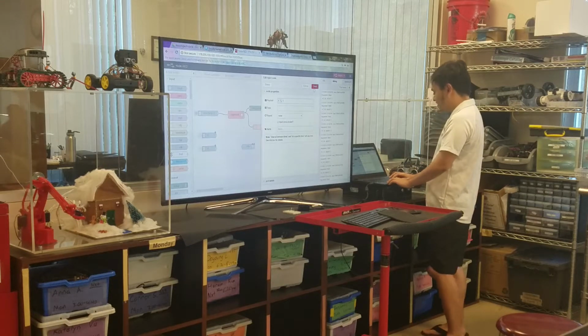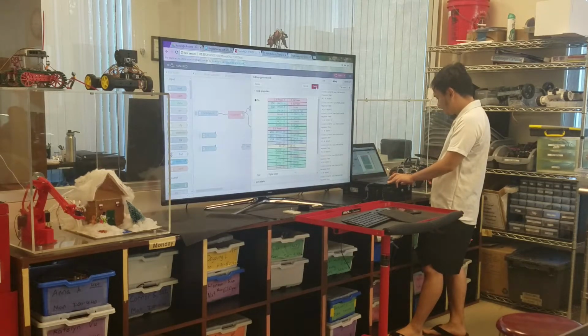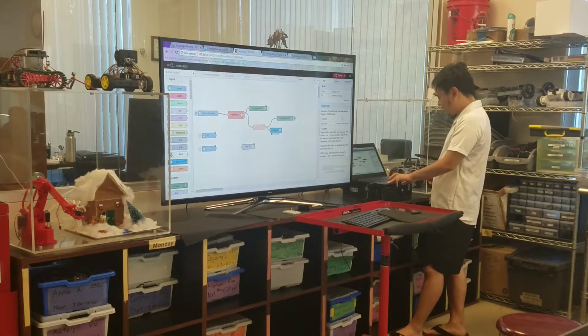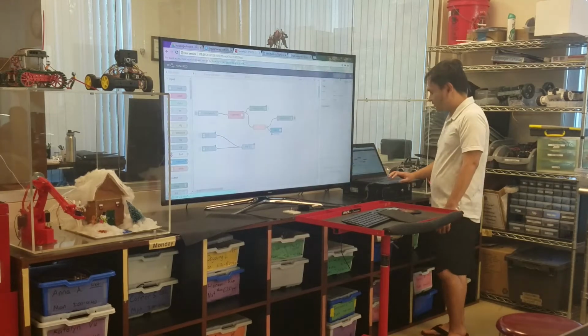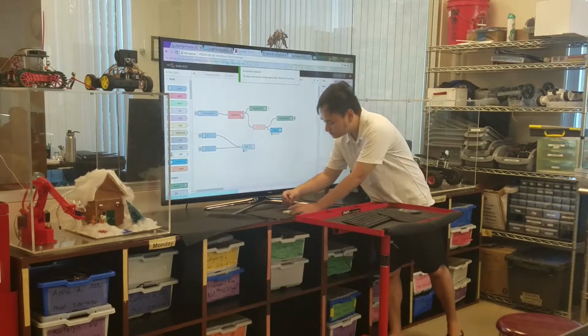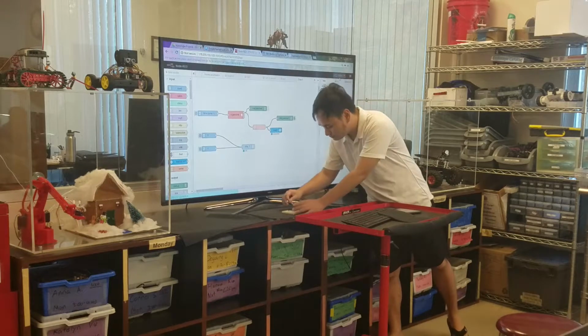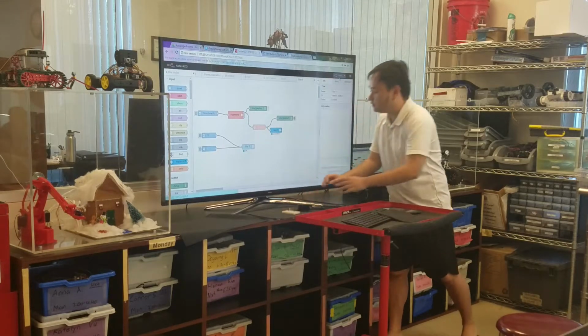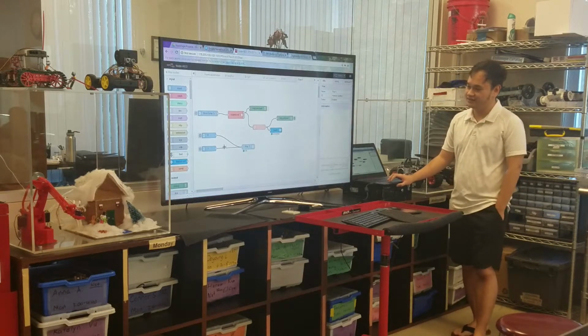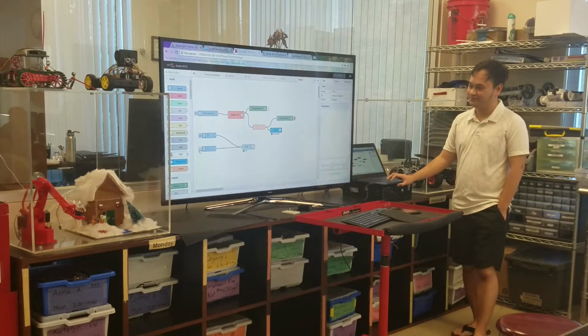And 1. So basically, in here, you look at the Raspberry Pi node. I set this one to pin number 7. It can only take 0 and 1, so that's why I put 0 and 1 here. You can manipulate the input and output later. Alright, and deploy. So if you want to turn on the LEDs, inject this one. Nothing happened yet.